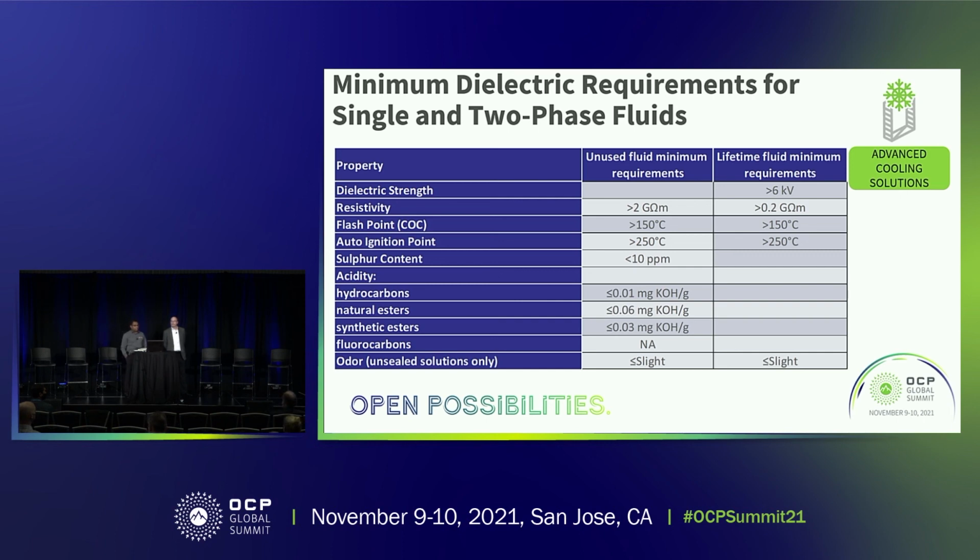So for sulfur, at least from the fluids that we deal with for the GTL, there is no sulfur in it because it's a material which is made of natural gas. But when you are dealing with synthetic hydrocarbons, if it is a crude derivative, you might see some. The reason why less than 10 ppm is listed here is because we need to have a test which can actually do the evaluation. If you are running a test which cannot detect that range, that's why it was specified as less than 10, so that when you run a test based on the methods that we highlighted in the previous slide, it can give you an indication of how many ppm levels we are actually seeing in the sulfur.